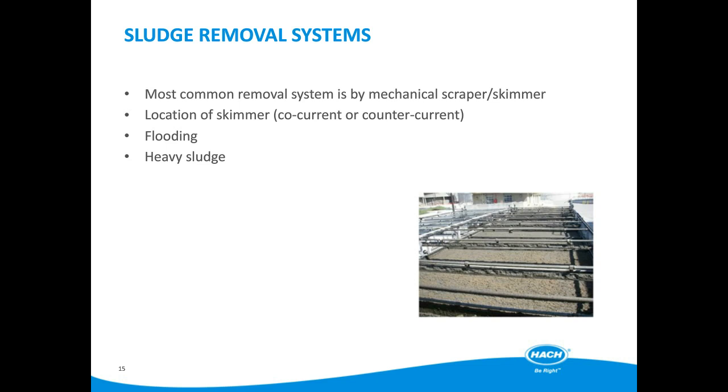Depending upon the influent water's properties, solids contents and the design of the DAF, a secondary sludge removal system usually exists at the base of the DAF tank. This normally consists of lamellar plates or could simply be settling cones.